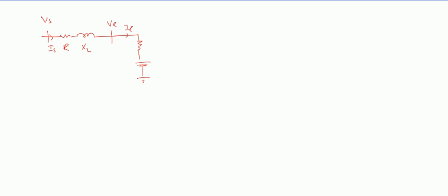Now let us make the phasor. So again we will take the reference phasor as VR. Okay. So now what happens? This is a leading power factor, a leading PF load is connected. So for a leading PF load, the current will be leading, right? So this is IR, and the angle between them will be phi r, the receiving power factor angle.